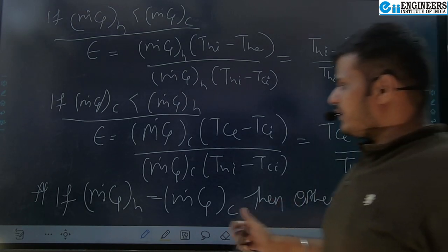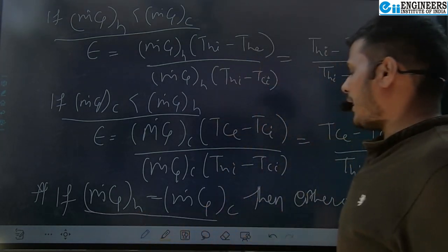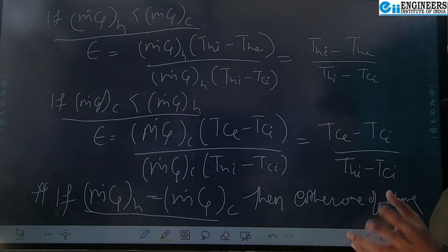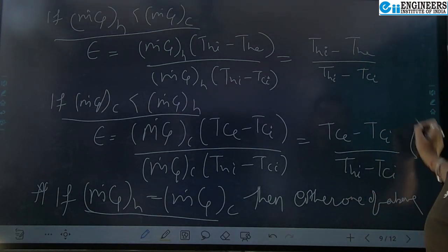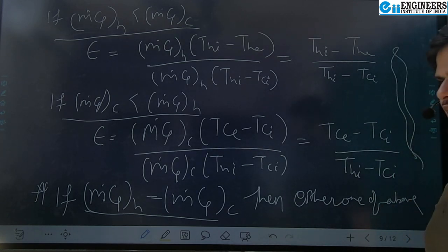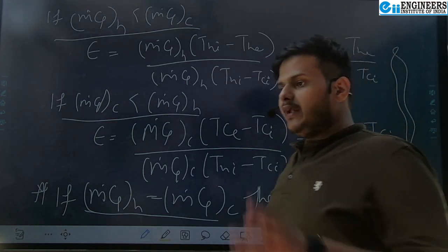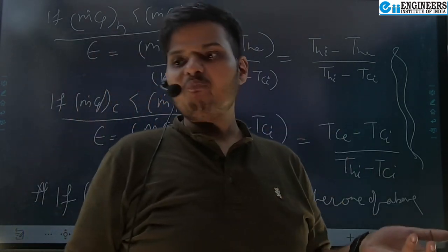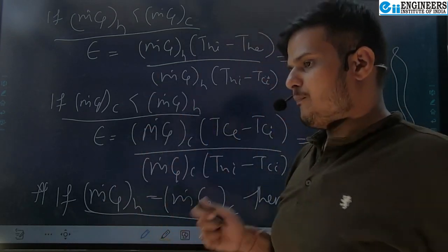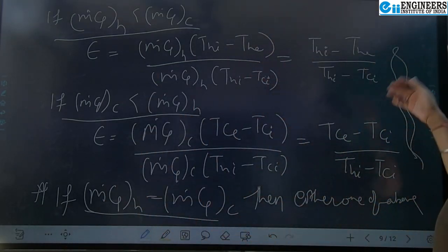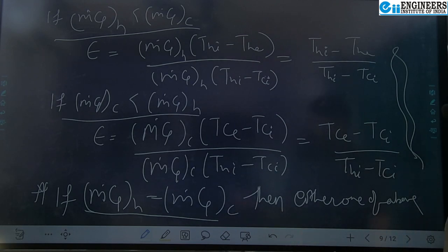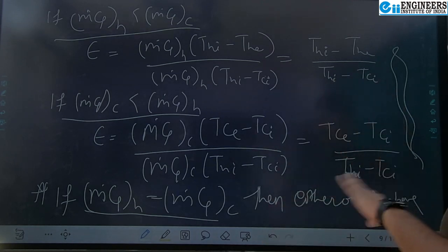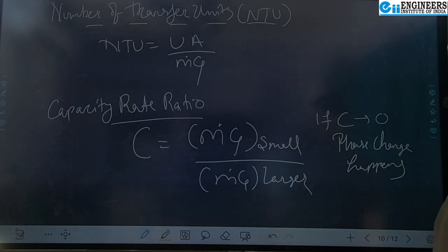Okay. If in this case the mass flow rate and the specific heat are the same for both the hot fluid and cold fluid, we can use any of these equations that we have determined. So here also, if a heat exchanger's effectiveness is given to you and you know any three of the temperatures, you can determine the other temperature of the fluid that is being driven in that heat exchanger. So with this we have come to analyze what effectiveness is.